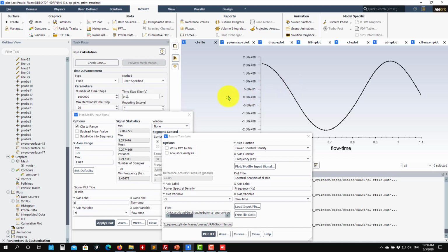So if you want to save your solution to do the animation, the plot and everything, you will need at least, let's say, 10. If you want to plot everything and see the full animation, as I mentioned, like 30. But for us to save the files, because those files are a lot of data, let me save with a frequency of 0.05.